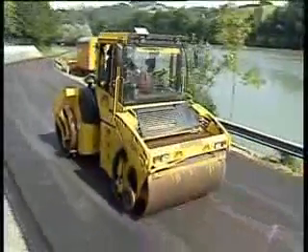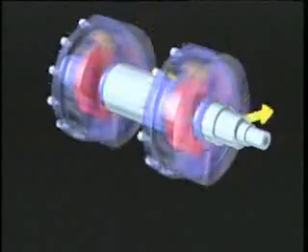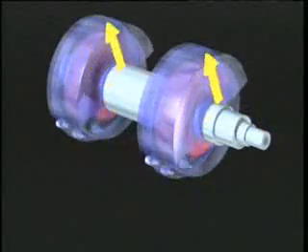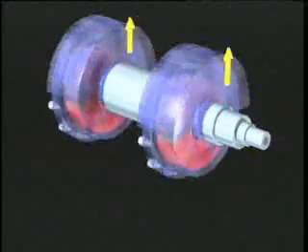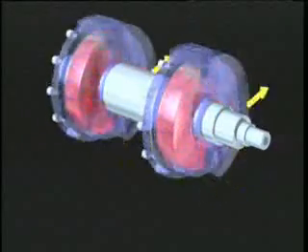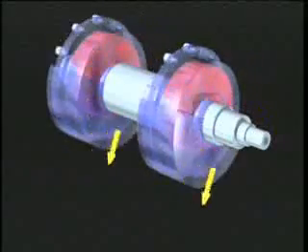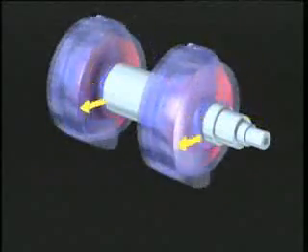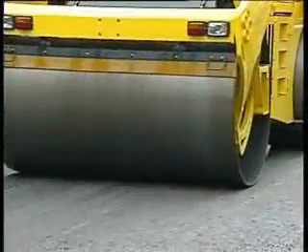How does the Asphalt Manager system work? With conventional vibrator systems, such as the circular exciter, vibration is created by the fast rotation of an eccentric shaft. When the direction of rotation changes, the amplitude also changes as the result of overlapping forces. Undirected movement occurs during compaction due to the interaction of the roller with the subsoil.